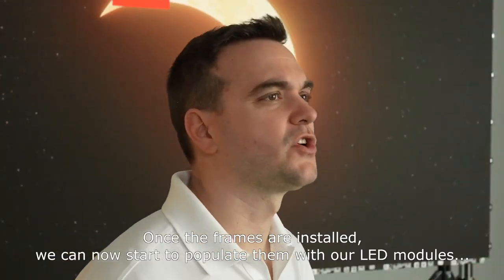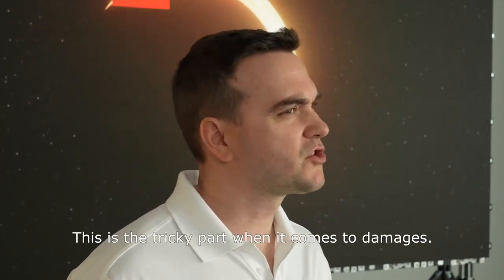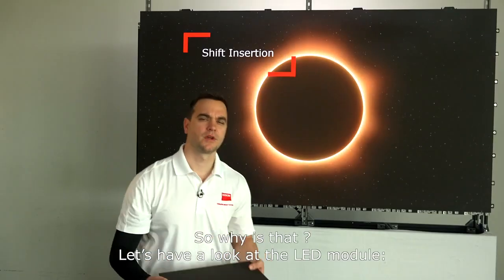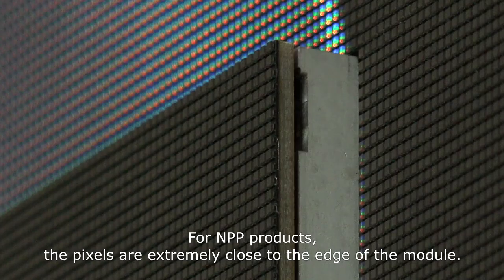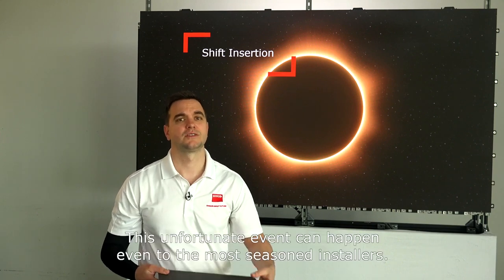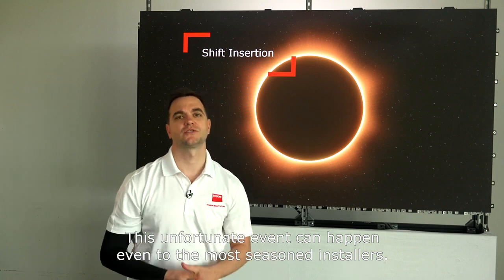Once the frames are installed, we can now start to populate them with our modules. This is the tricky part when it comes to damages. So why is that? Let's have a look at the LED module. For narrow pixel pitch products, the pixels are extremely close to the edge of the module. Even the slightest contact between the edge of the module and its surroundings can rip off multiple pixels. This unfortunate event can happen even to the most seasoned installers.